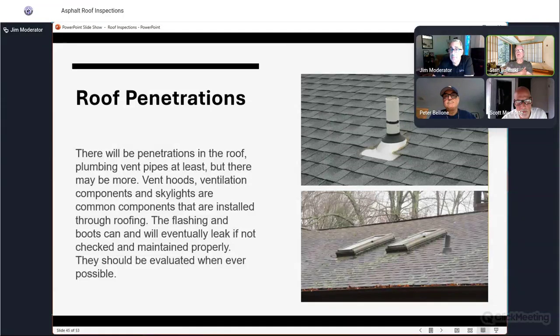Roof penetrations. I don't know how many times you find the boots, the neoprene fatigued and cracked or stretched or warped. Got to be careful with skylights and the curb box. Those you can see from underneath. And what I find a lot is if you're not looking close and not shining your light on an angle, a lot I find have been patched and painted.